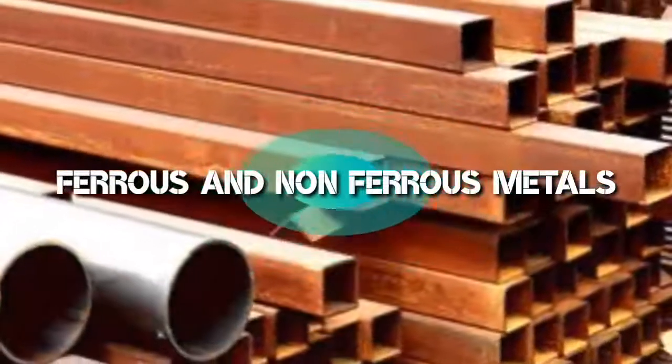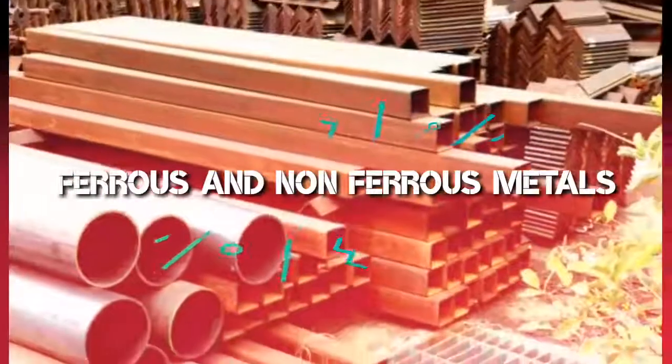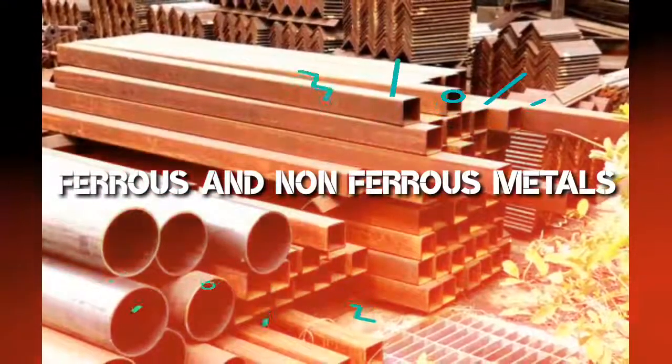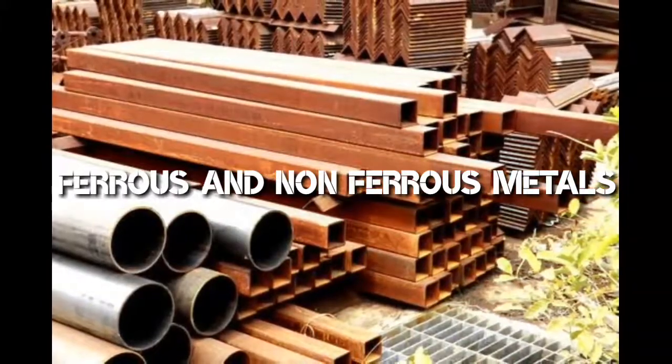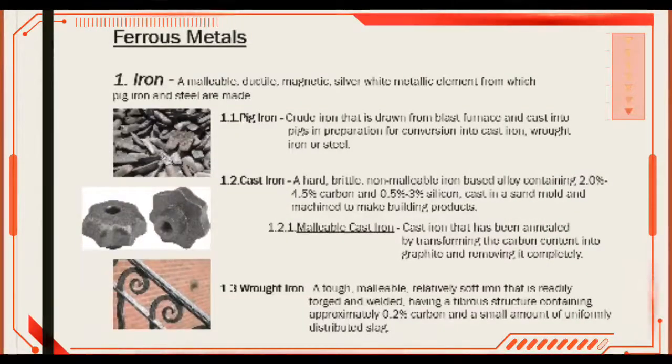A ferrous metal is a metal containing iron as a principal element, while non-ferrous metal is any metal containing little or no iron. Now let's talk about ferrous metal. Iron is a ferrous metal. Pig iron is crude iron that is drawn from a blast furnace and cast into pigs in preparation.